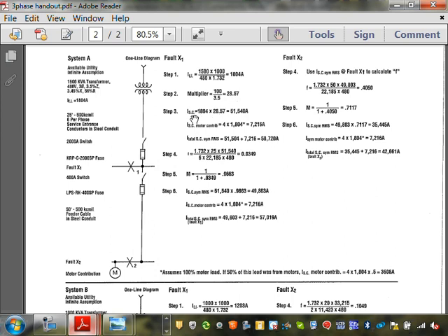Then multiply this multiplier by the full load current. Then at the secondary of this transformer, right in here, guys, if I am to take phase A, phase B, phase C, tie them together, flip the switch, you will be encountering, what is it, 56 or 61? 61.5 thousand amp. That's how we do the calculation at the secondary.